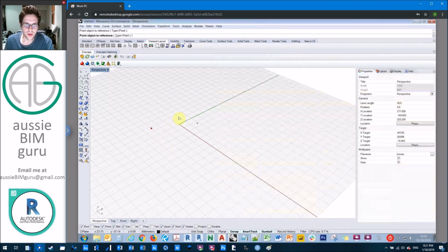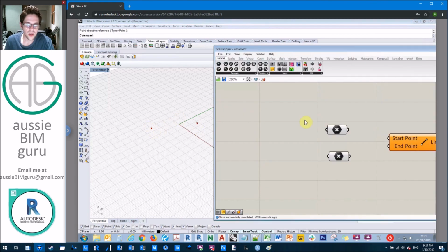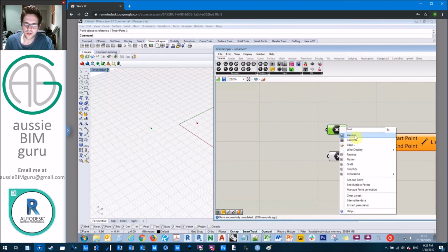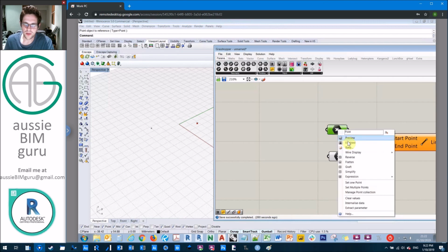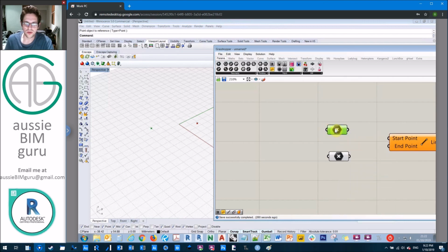And you'll see that Grasshopper previews the points with a cross. You can change what the points look like under your display options. But you can also right click on nodes and turn off their preview. And you'll see that now we no longer see that output. So it's up to you how many things you want to preview during the course of your script. But every single node that collects data that's geometric will display a preview in Rhino. But note that it's only temporary. It's not creating a permanent point. It's just creating a point visually.